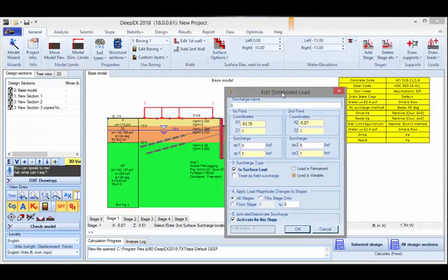click this dialog appears. Here I can define the x coordinate of the start and the end of the load, x1 and x2, and also the load magnitude. So here if I start it from -60, and let's say that it goes until 2 feet behind the wall, so I will take it at -2. I remind you that 0 x coordinate is the top left point of the wall. I can also change the magnitude to something else. I will change it to 0.6 ksf.